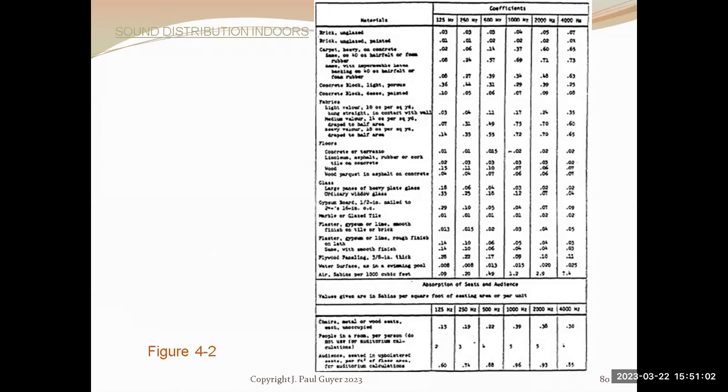In the commercial arena, the suppliers of building materials have, to a very large degree, gone out and had independent testing laboratories like Underwriters Laboratories field test these construction schemes and determine what the sound transmission coefficient, the single number appropriate for that wall construction system.